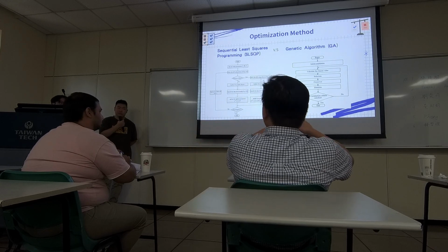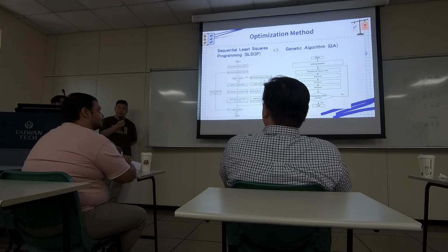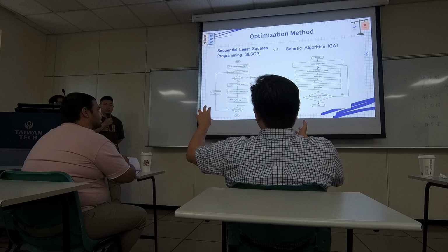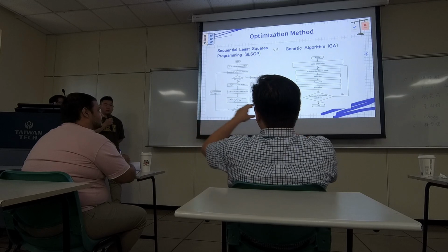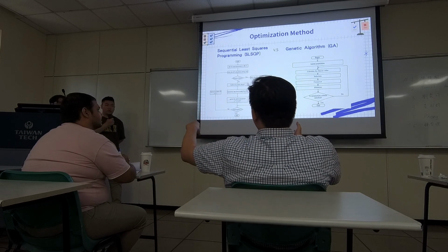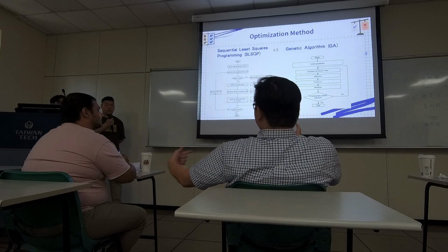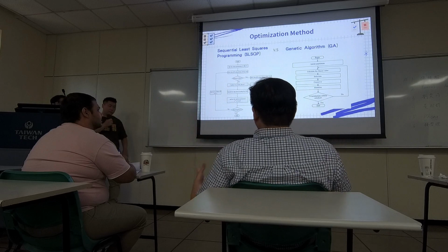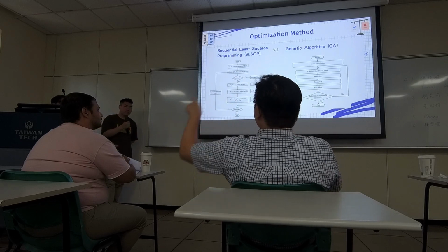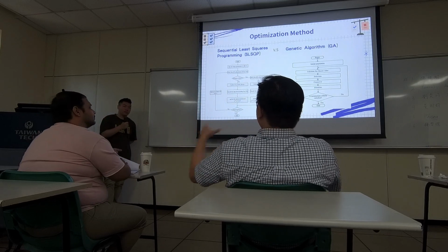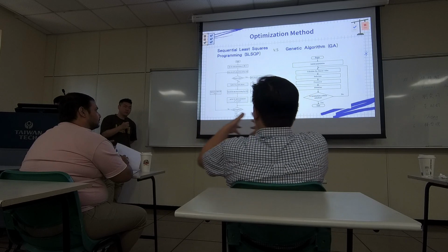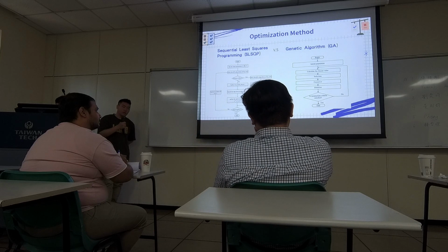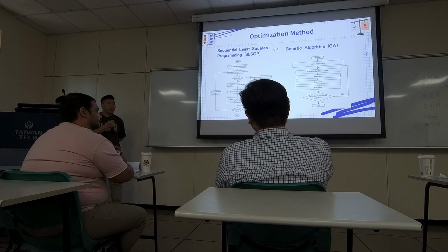So my contribution was the MATLAB code. That MATLAB code generated the finite element script, so it automatically called ANSYS, ran the finite element, and got the result back. So then my entire package automatically ran finite element. The MATLAB code did the optimization, and the finite element got the performance. But if you want to do that, it's very difficult.